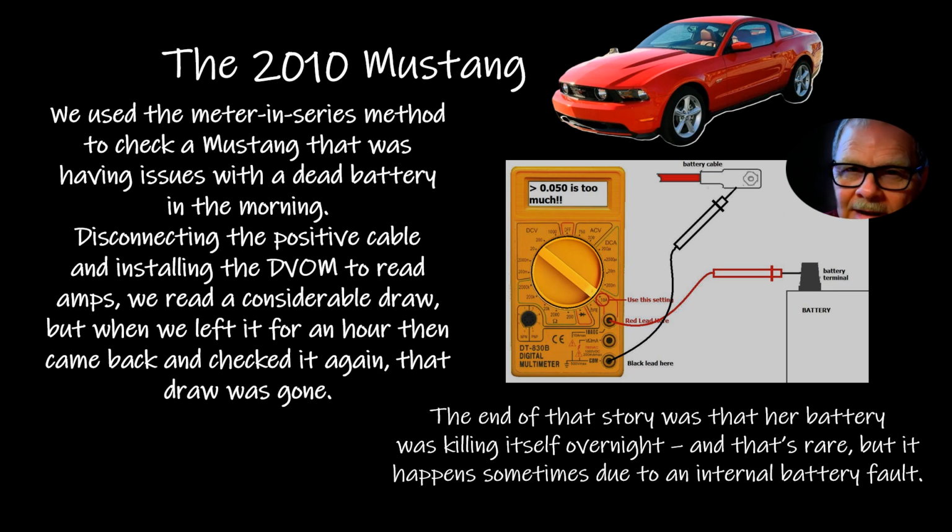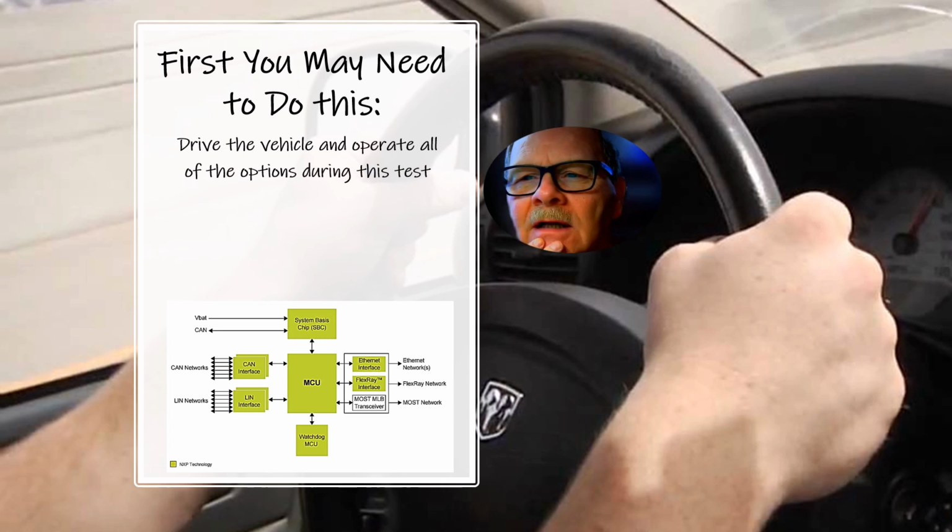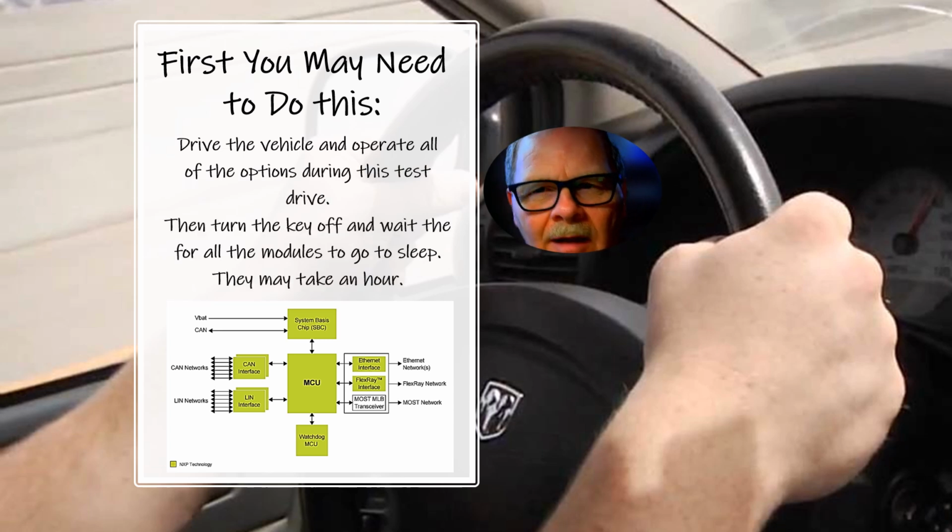We let all the capacitors charge up on all the modules on that 2010 Mustang. It turned out that the battery itself was the problem. We could have done a whole lot of work if we weren't patient and if we didn't walk away and just wait. That's what you need to do. Now, you may need to drive a vehicle and operate all the options during the test drive, then turn it off and wait for all the modules to go to sleep.